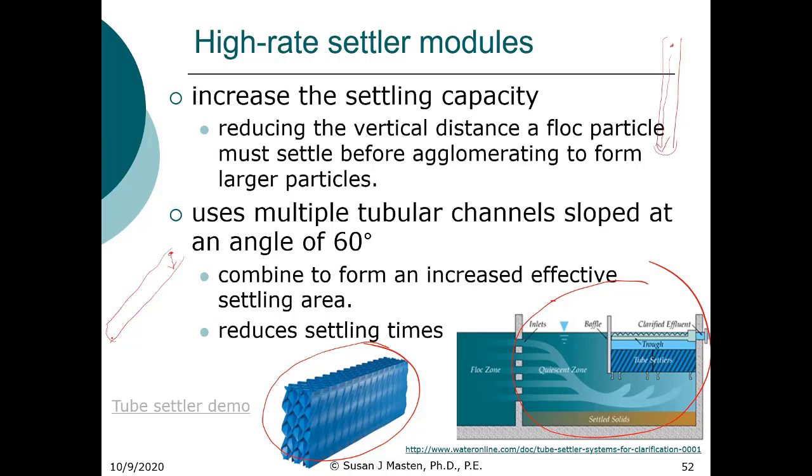So it actually does significantly increase the settling time, because, we can kind of see it here. Okay, it only has to settle this short distance, and then it's going to fall down here. And then once it hits that floor, then you're going to also get flocculation, and you're going to get larger particles. So it will allow it to form larger particles, which will also settle faster.